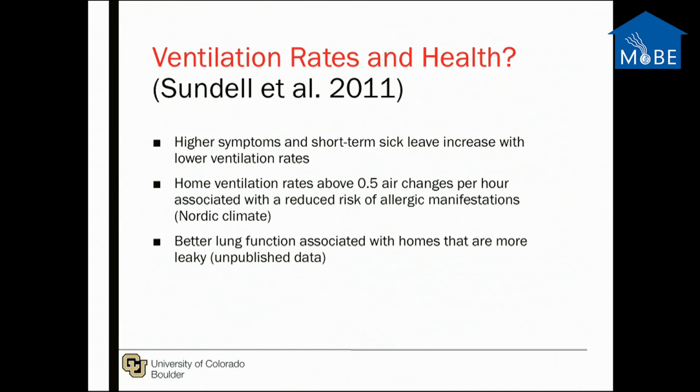It's very clear from the research that higher ventilation rates are associated with reduced prevalence of sick building symptoms. It's also associated with reduced inflammation, respiratory infection, asthma symptoms, short-term sick leave. All of this is related to ventilation rates. And if we can get the ventilation rates up to 25 liters per second per person, we see these health